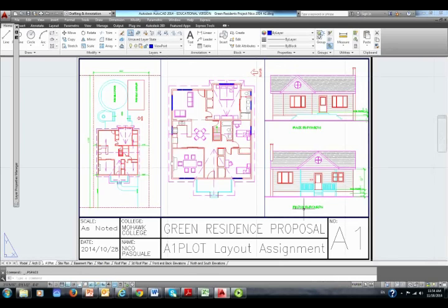all you need to do now in paper space, you could copy the notes. You could make the standard bubbles. What we need to add is that this is site plan scale 1/8 of an inch, main floor plan 1/4 inch, standard residential scale, front and back elevations 1/4 inch scale. As far as I'm concerned, I'm happy. You could probably jazz up your notes. Maybe we'll review this.